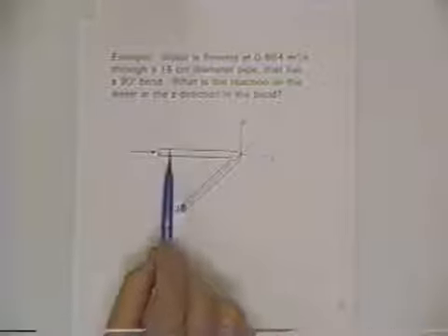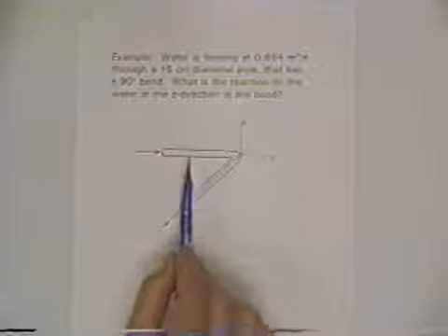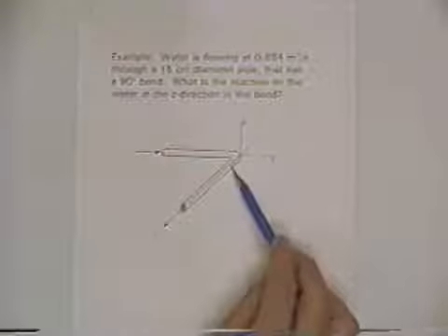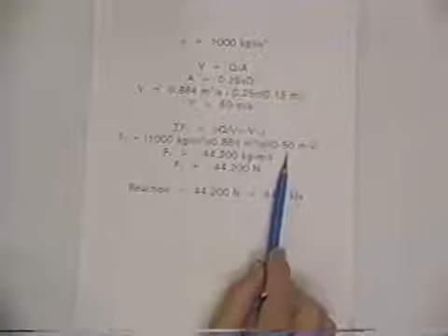Of course there's a velocity in the x direction, but in the z dimension there's zero velocity going in, and whatever the velocity is in the pipe coming out will be in the z direction. And so we've got 0, and again we all realize there's an absolute velocity of 50 meters per second, but when we divide it into the vectors of directions, in the z direction there's 0 velocity going in, and then coming out of that bend, that control volume, is 50 meters per second.